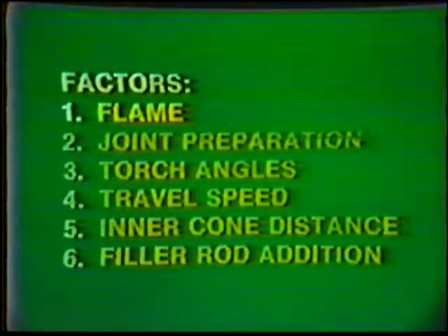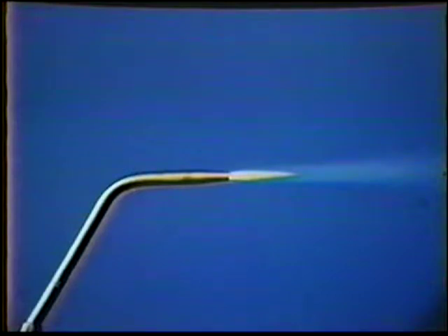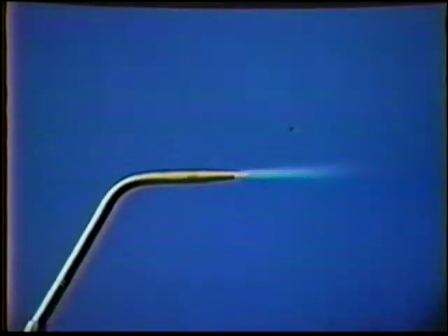The flame must be adjusted to suit the requirements. A carburizing flame is used for most brazing operations. A neutral flame is used for fusion welding. And an oxidizing flame is used for braze welding.